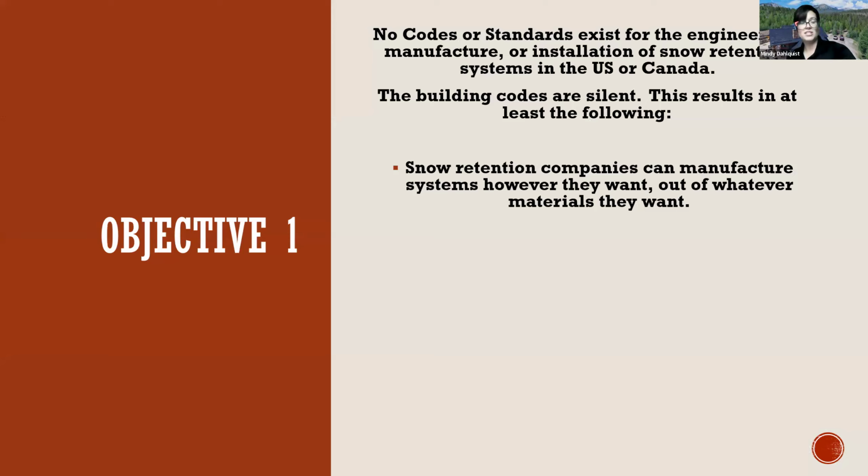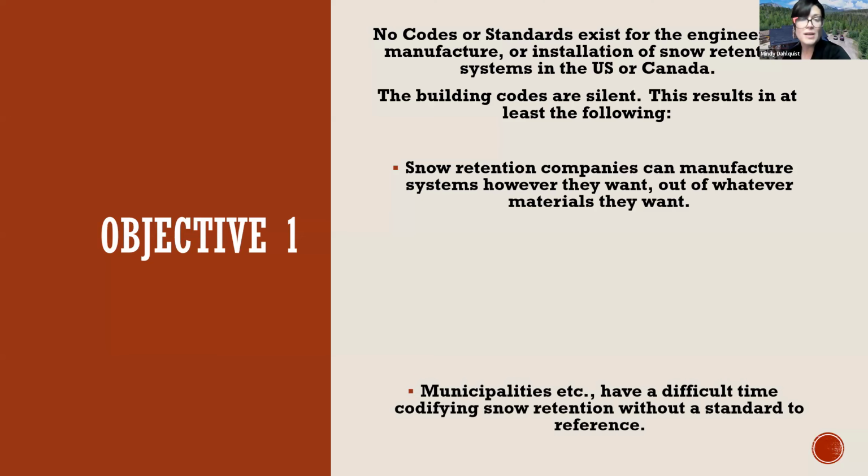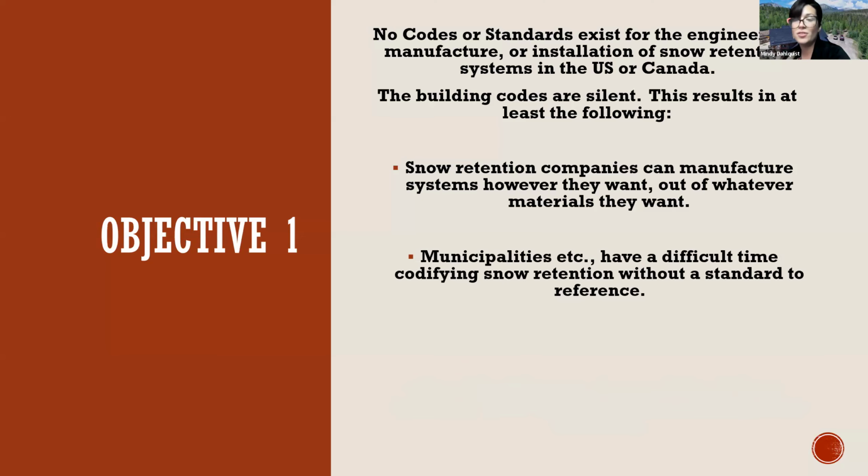So I have just a coffee cup sitting here, a paper, cardboard, whatever it is, coffee cup. And if I wanted to take this and sell it to you and say, if you super glue this to your roof, all over the whole entire roof, this is a snow retention device. At this time, there is no standard to say that that device will not hold snow back. So it's really important to make sure that you are dealing with the correct manufacturers who test their products and all of that to make sure that that product is actually going to be substantial enough to keep the snow back and to remain safe on your roof.